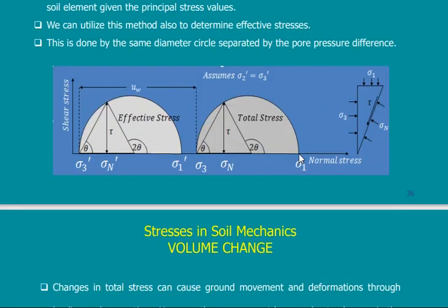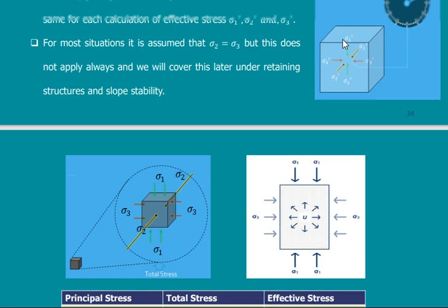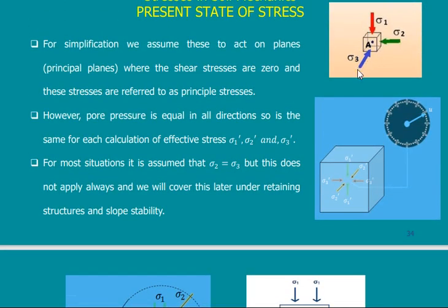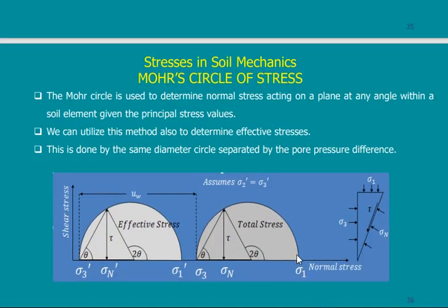So Mohr presented this drawing. In this drawing, on the normal stress axis, I just put the value of sigma 1 and the value of sigma 3. This is the high value of stress here, and sigma 3 is the low value of stress on this particle, and I draw a circle. When I draw a circle, if I go horizontally tangent to this circle, then this will be the shearing stress that would cause failure.